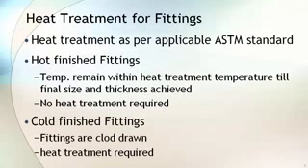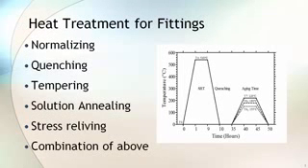If fittings are manufactured by the hot finish method, heat treatment is not required. However, for cold finish fittings, heat treatment is required as per the applicable ASTM material standard. Common heat treatments performed on fittings are normalizing, quenching, tempering, solution annealing, stress relieving, and any combination of these.